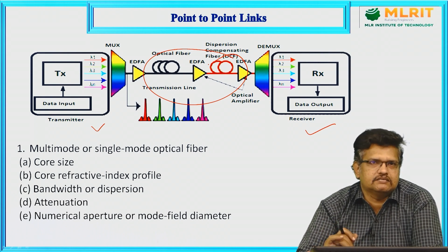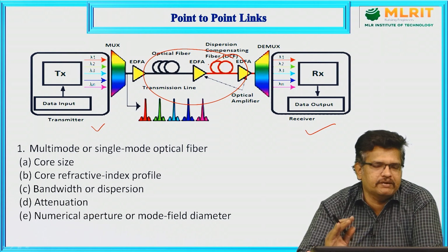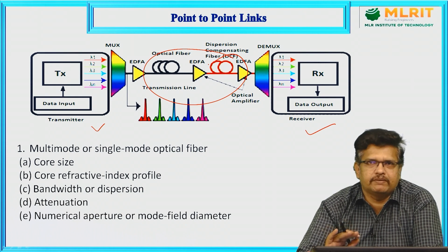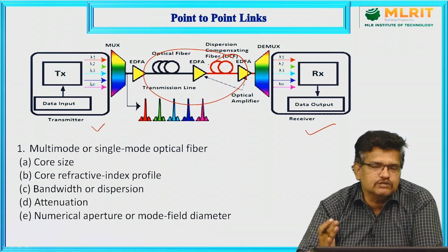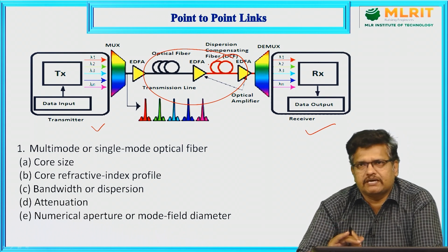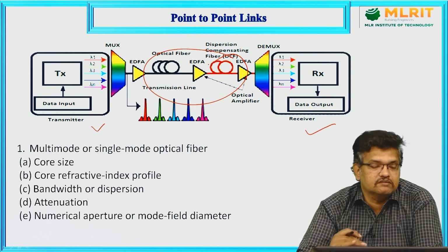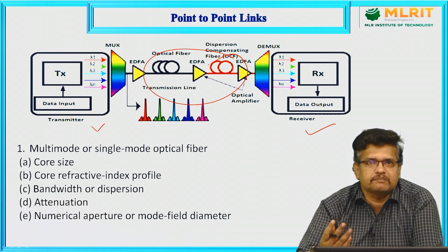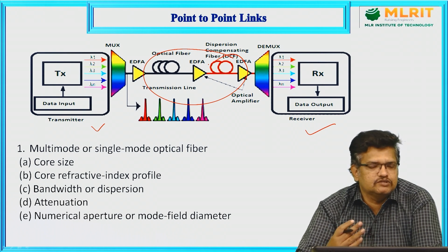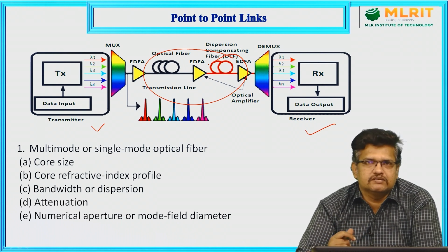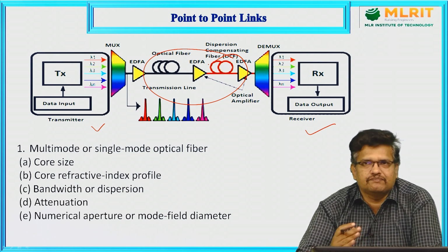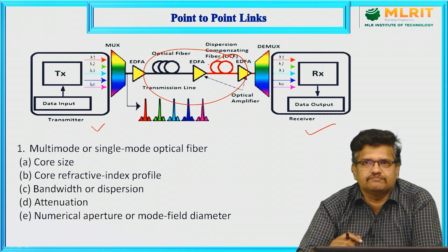see the conditions. Suppose in fiber type, in optical fiber communication I am using the optical fiber, that is compulsory. So while choosing a fiber is also a major condition. Whether we should use multi-mode fiber or single mode fiber depends upon the application. The designer has to think carefully and choose the fiber according to the needs.